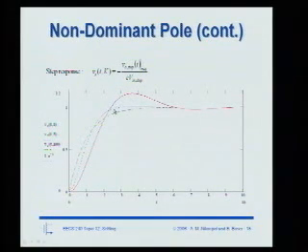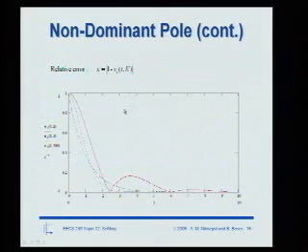And so what you have to do is zoom in to this point. So this is a plot of the error, basically. It's 1 minus the actual step function, so this is the residual error, and again as a function of k. So here again is the case where there is no second pole and it decays simply exponentially. Case where the second pole is very far away from the unity gain frequency of interest. And then here is the case with 3 versus 1.